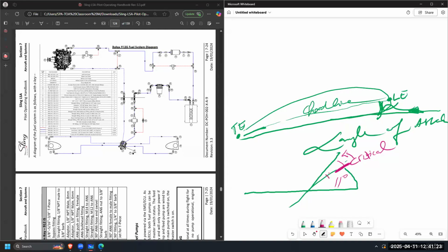This one at the limit here is 15 degrees. If you exceed 15 degrees, you're getting into the so-called critical angle of attack, let's say 25. These are just rough numbers, okay? This is not one-to-one. You exceed your critical angle of attack, and what happens?